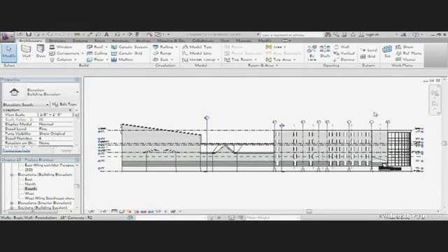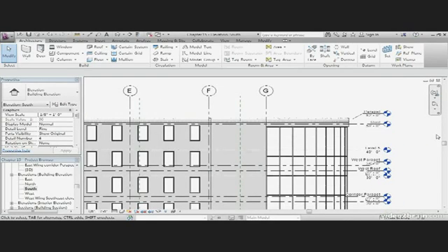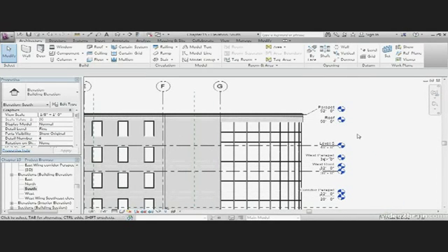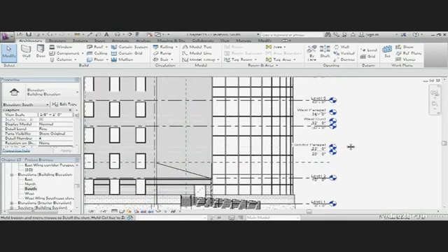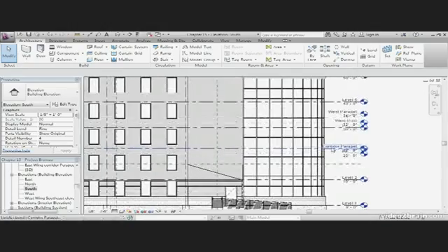In this lesson, we'll learn how to constrain our walls to specific levels. Since we have levels, it's time to talk about using them. Levels drive Revit. They also control how our walls begin and end. Every object in Revit knows which level they're hosted by.